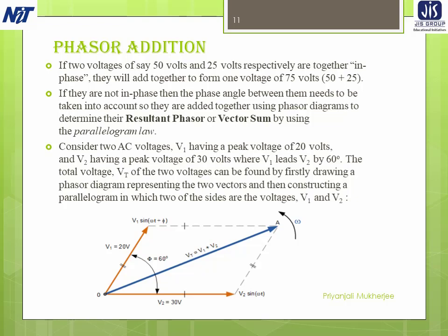For the series circuit in which current is common to all parts of the circuit, the current phasor is usually taken as the reference phasor. For the other phasors, the same diagram is drawn on the horizontal line.